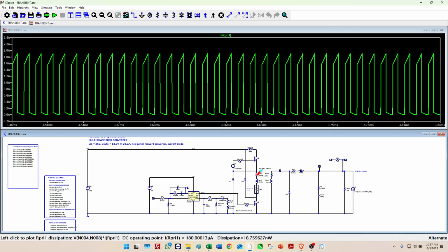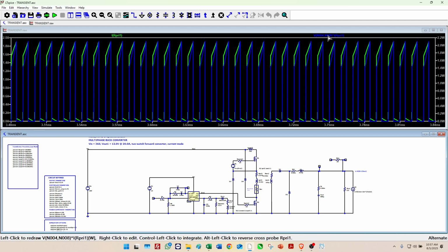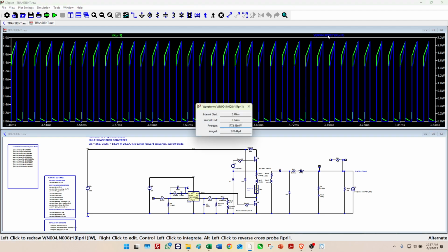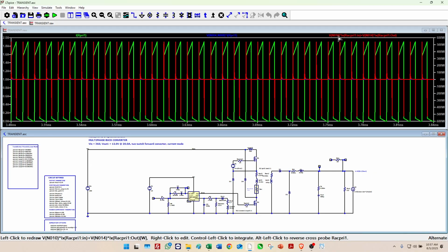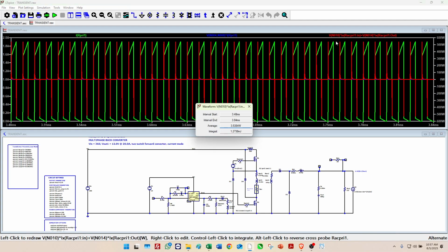Now let's look at our losses. So here is the loss in the primary resistance. This is just the DC resistance, which would tell us the same number that RidleyWorks told us. It's about 0.77 watts. And then the loss in the AC resistance, we click on that other element, it pulls out the AC resistance loss. And now we see there's actually 3.5 watts.